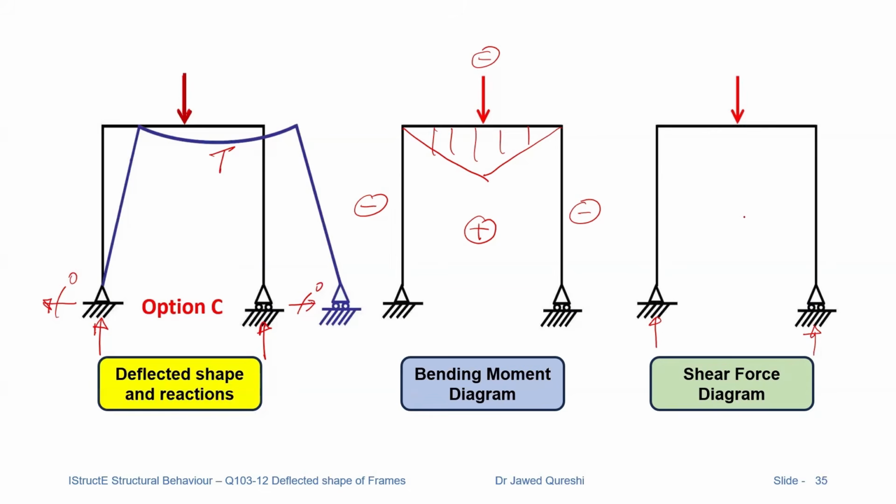And remember that in case of shear force, we draw negative inside and positive outside. So starting from right side would be our best option. So from right to left, it's creating anti-clockwise. So anti-clockwise is drawn positive.